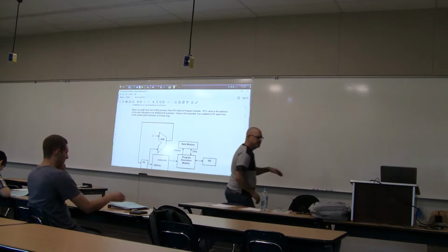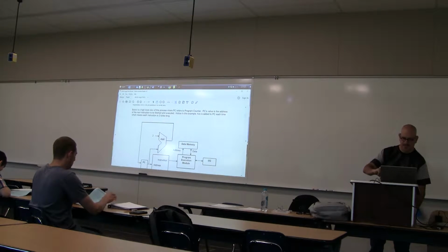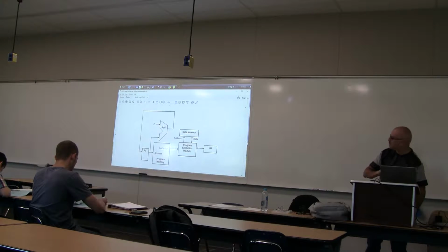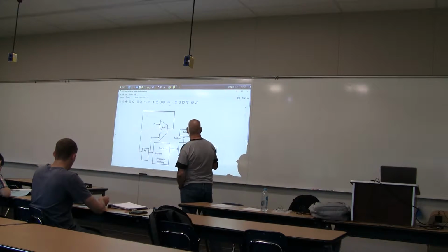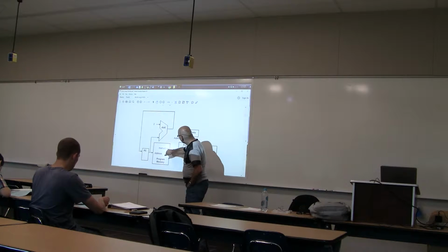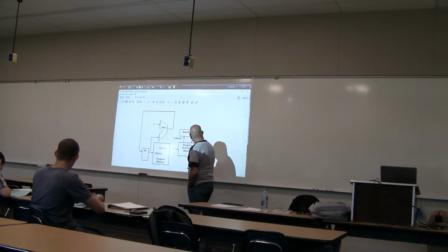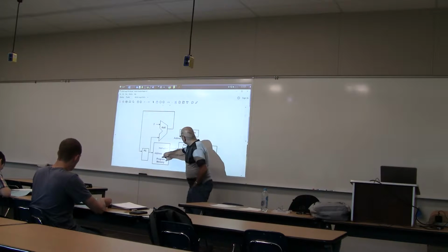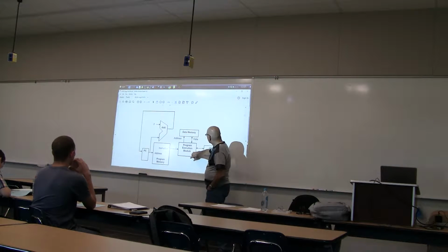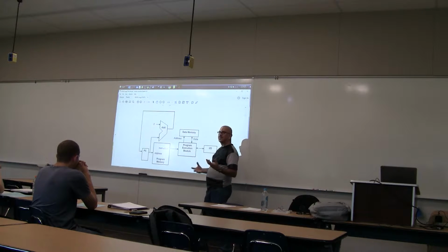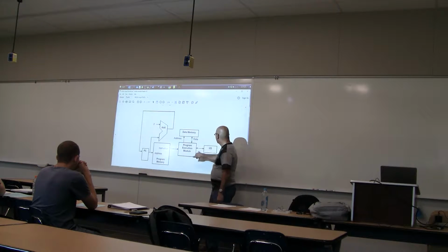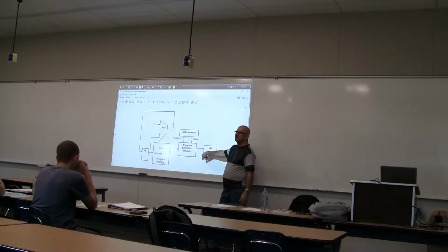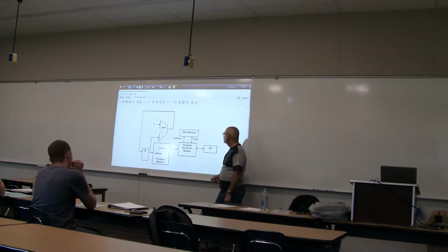So just to show you a view of what I was describing a little while ago, this is the most simplified view of inside the PIC processor, right? There's your program memory. This is the thing that actually grabs an instruction from memory, and it can access a data memory, a thing where we store information that we want to manipulate, and it can read data, make changes to it, and write it back. It can also interact with the whole I/O subsystem to get to things outside of the chip.